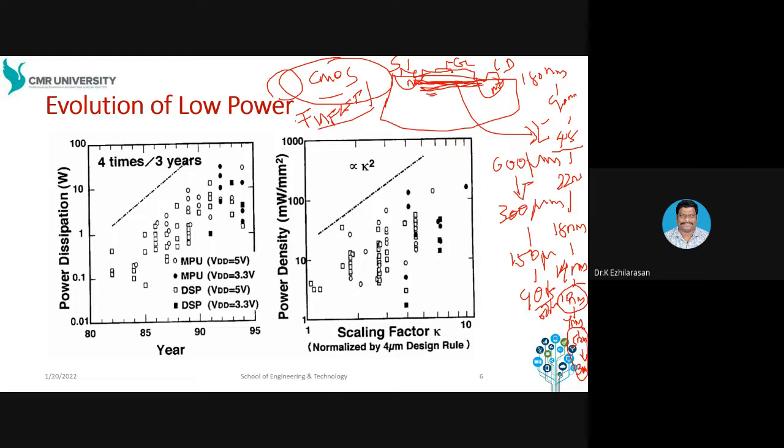One more thing I need to say: when you are going to design any circuit, the very important key factor is testing. Say you are going to design one circuit, and the input is 4 bit. Take the example of a 4-bit AND gate. You need to test whether your AND gate is working properly or not. At that time, you need to give all the 4-bit input cases, around 16 combinations.